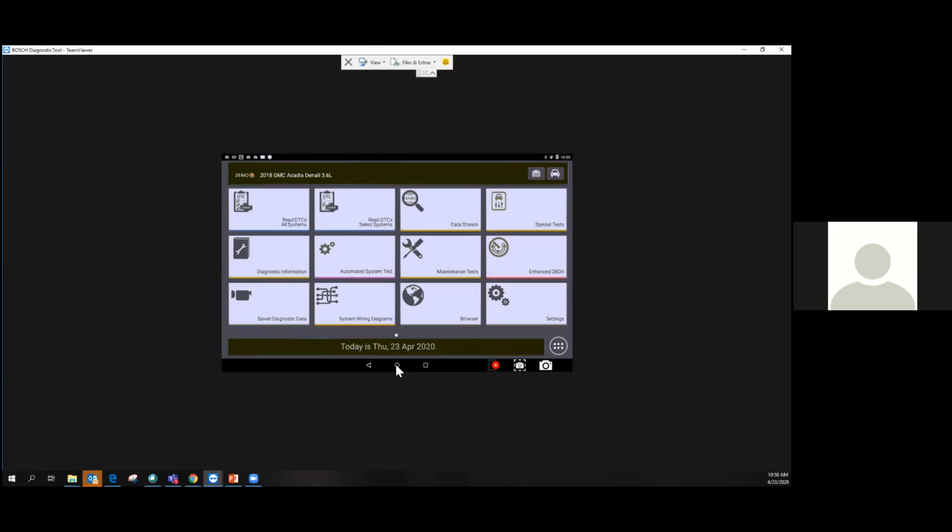You know, you'll be able to talk to a couple of modules, right? Things like body control modules and stuff like that. They are awake at all times, right? Because they control things like lights and door locks. But that's not going to get you where you need to go. So you can always attempt to manually get into a specific module, but the first thing this tool is going to try to talk to is that ECU, right? That's usually the main hub of these systems. So in short, without key on, engine off, your scan's probably pretty ineffective.